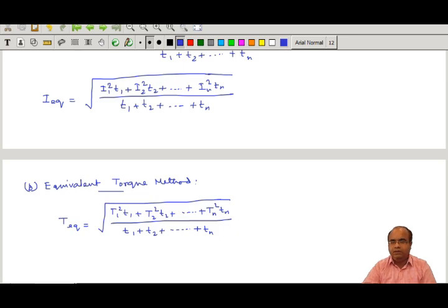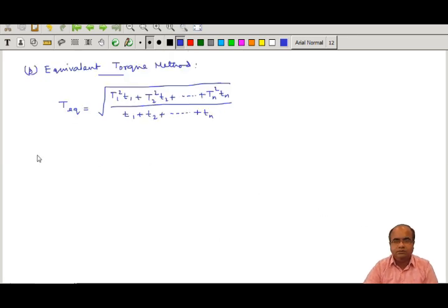Okay. Now, if the motor speed is constant, or the variation of the speed depending upon the load does not vary much, then we can consider constant speed operation, and for that the equivalent power method can also be applied to find out the motor rating.